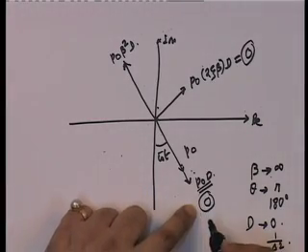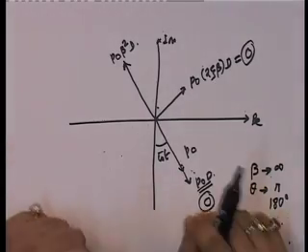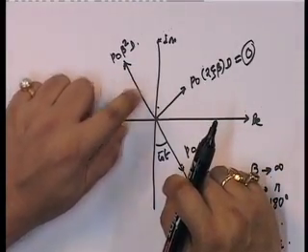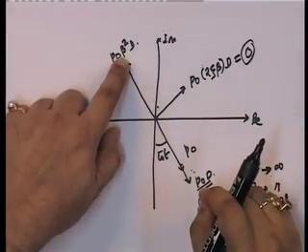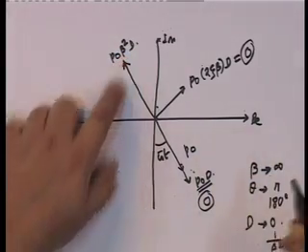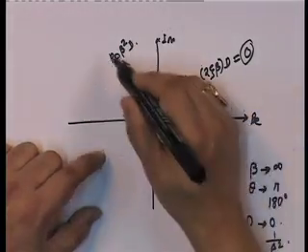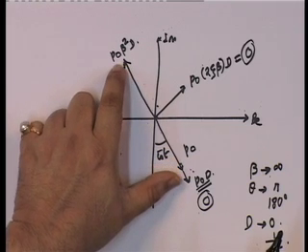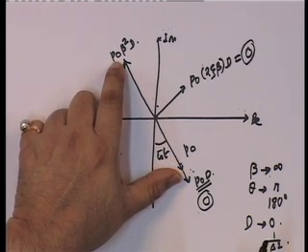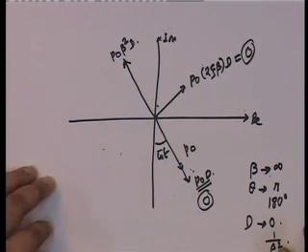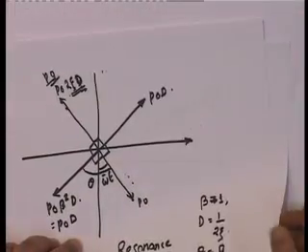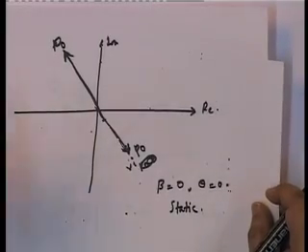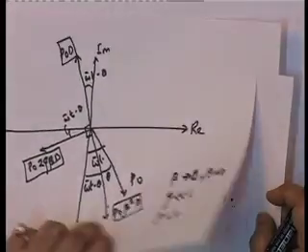So, if you look at this, the elastic force is 0, the damping force is 0, and what resists the applied loading? It is the inertial force that balances the applied load, because beta squared D goes as 1 upon beta squared. Remember, we had done all of this a couple of lectures ago. The elastic force is 0 because the applied load is completely resisted by the inertial load. So, you see, the Argand diagram actually tells you many very interesting things about the kinds of mechanisms that you have for various kinds of situations.